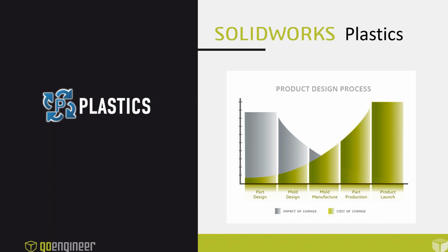So generally speaking, when we talk about plastic injection molding, there's some standard information in there, and that's kind of what this graph is showing: early on in the manufacturing phase, let's say in the part design phase, making subtle changes to draft or ejection pin locations or just the overall shape of the part is really easy, and it hardly costs any money, right? So you can make a whole lot of changes without impacting the financial bottom line of that project you're working on.